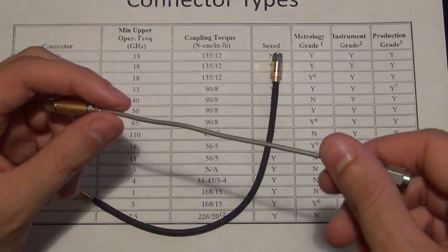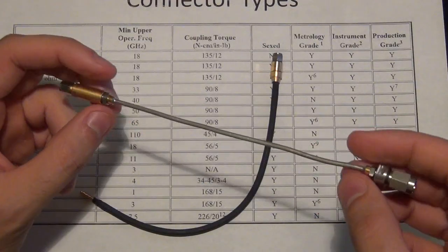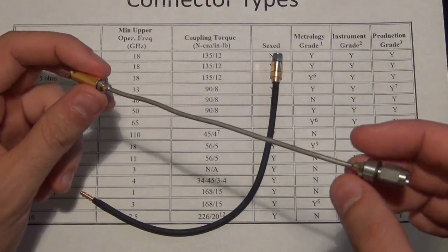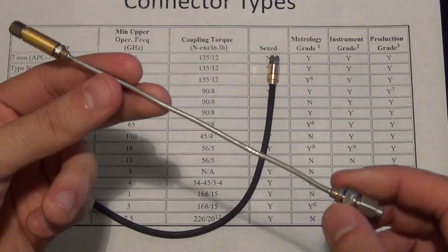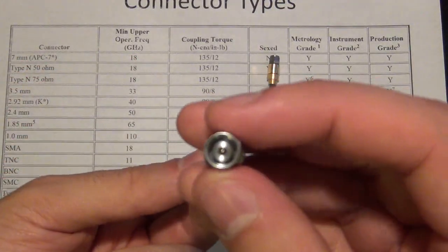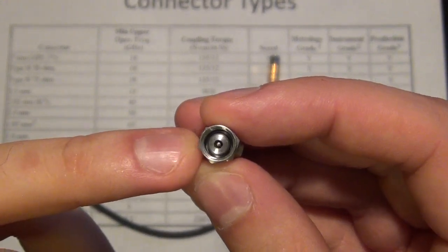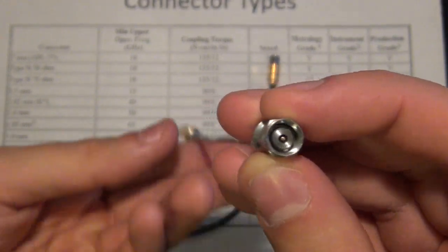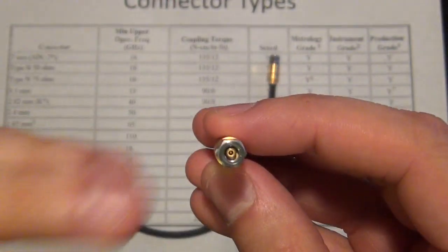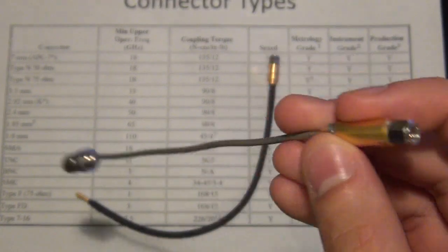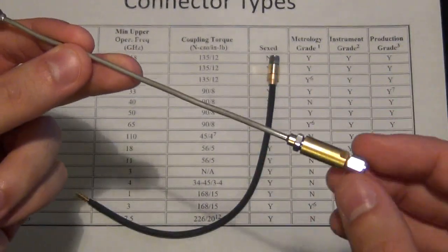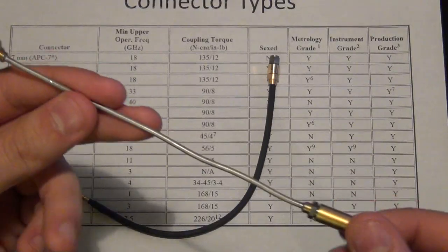You can't really reuse those. They're very good. They will give you stable measurements, but only once they're basically set in their place. So this is one that I've taken from the lab. Again, because it is ending in a V, this particular connector will only work up to 65 gigahertz, even though on the other side of it you have a 110 gigahertz connector. So this cable is just converting from 1 millimeter to V.